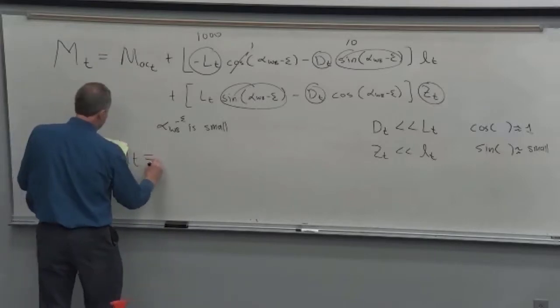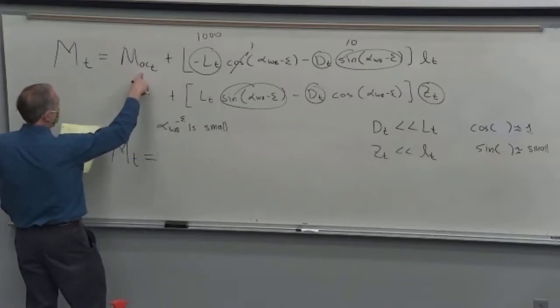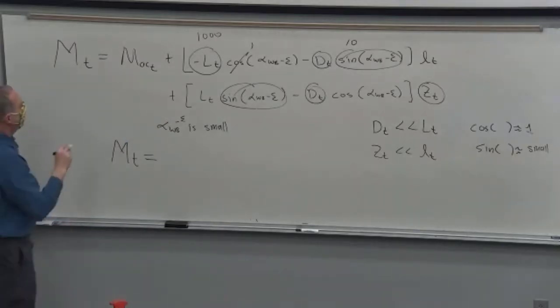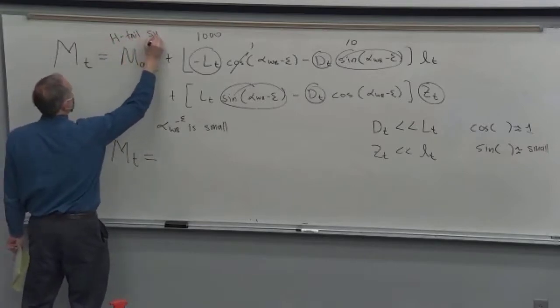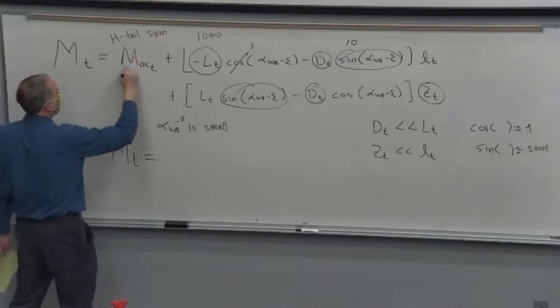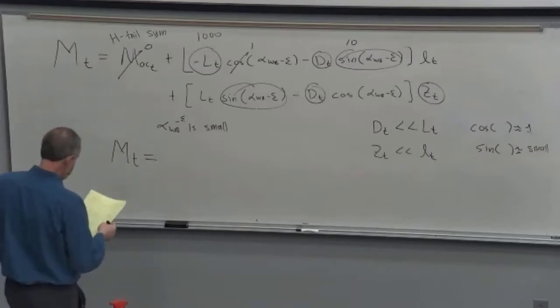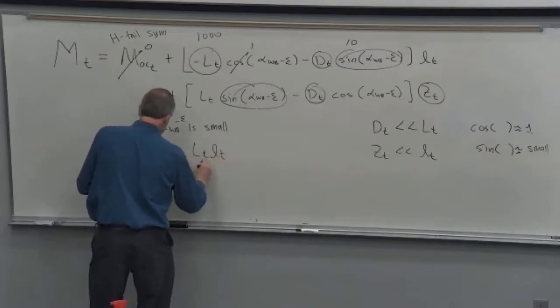is the moment of the tail. Oh, by the way, what happens to this? Is that small or not? Depends. Typically, the horizontal tail is symmetrical, which means this is small or 0. So in the book, he throws that away as well. He says you almost always make a horizontal tail out of a symmetric foil because there's no camber. Lots of approximations.